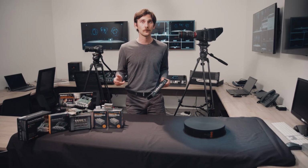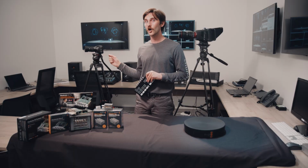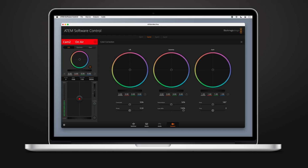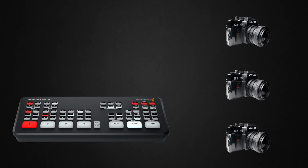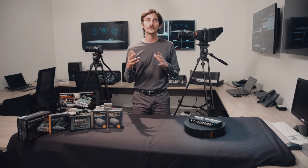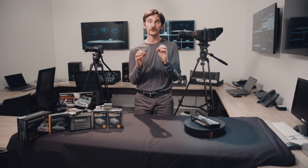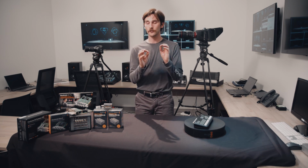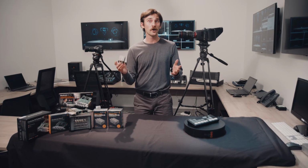The HDMI model, when paired with the Blackmagic camera, also takes full advantage of the incredibly granular camera control unit within the ATEM software. With the SDI model, you need to redistribute one of your SDI outputs back to all of your cameras with a second SDI return cable. Whichever model you select, you needn't worry about feeling locked in, as you can bring any camera feed into your system with the appropriate Blackmagic converter, which we'll talk about more later.